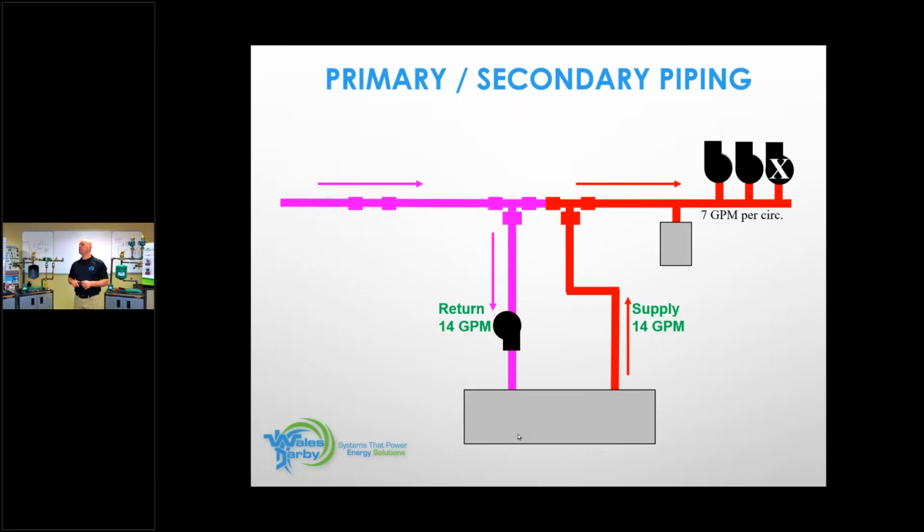Scenario number 1, go. Just a question that came in, and it reverts back to when we had multiple boilers, primary, secondary. At the boiler, does piping length matter if there's more elbows, say on one boiler versus the other 2 or 3? Yes. Great question.